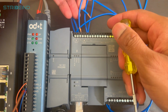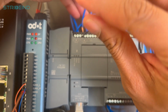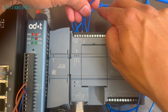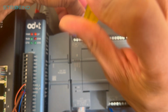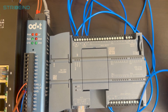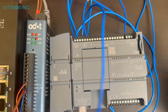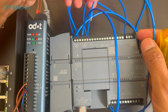Now we need to wire this up. We need to connect positive and negative to the PLC. We can use this 24 volt output from the PLC to supply the signal generator. Generally your potentiometers are 3 wire. You need one positive, negative and output signal from the potentiometer. So these are 3 wire devices. The third wire will be connecting to the analog input module. So positive and negative will be connecting to a power supply, and the signal part will be connecting to an analog input module.